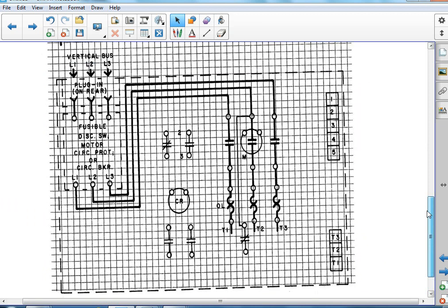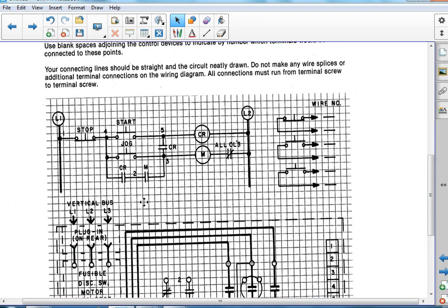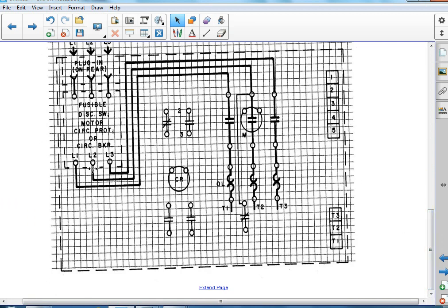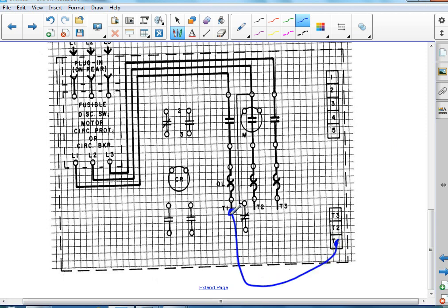Oh, that looks good. So now we have a wiring diagram we're doing, but our push buttons are one place and our controller's in a cabinet. And there's wires that are 500 feet long connecting the two, and we have to be able to say what we're doing. Okay? All right, so first thing we're going to do is we're going to hook up T1 to T1 and T2 to T2 and T3 to T3. So we're gonna hook up those guys first. Now at least I have power.